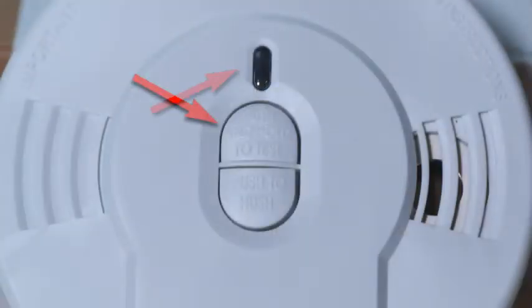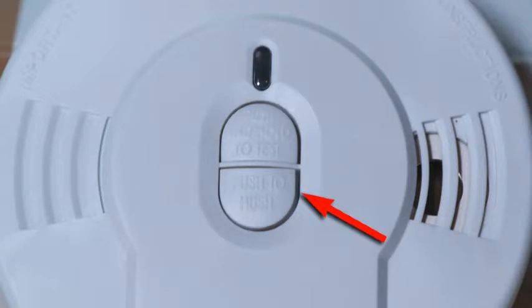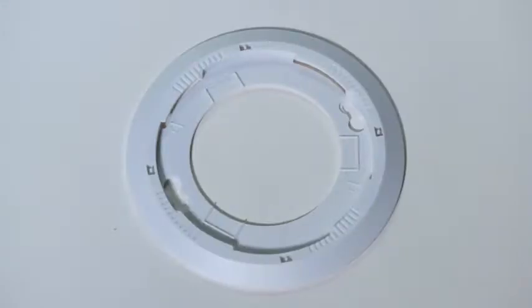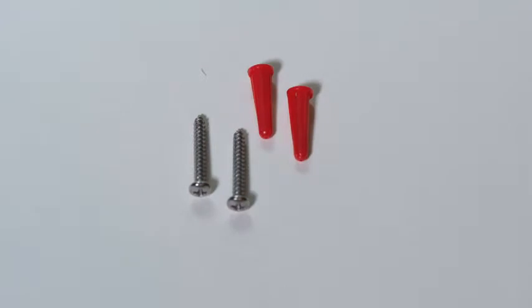The alarm features a test button for monthly testing and an LED light allowing simple verification that the battery and the smoke alarm are operational. The smoke alarm has a smart silence or hush button with which the alarms that have been verified by the owner as nuisance can be silenced. The smoke alarm has a mounting bracket and requires 2 Phillips head screws together with 2 optional anchors to secure the base and the alarm to the chosen location.